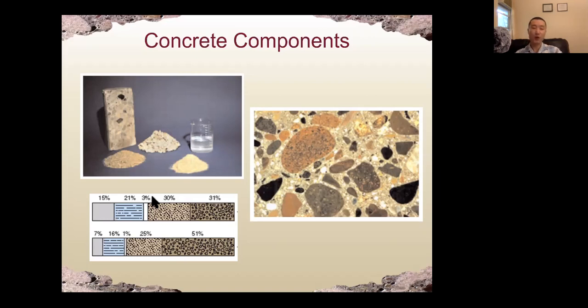Okay. The reason we put water in concrete is that water will have a chemical reaction with cement powder to generate strong materials. We call that CSH. Okay. We'll discuss the chemical reaction of cement powder with water in future lectures. Water can also control the cost of concrete, control the strength as well as durability of concrete, and also control the so-called workability of concrete.